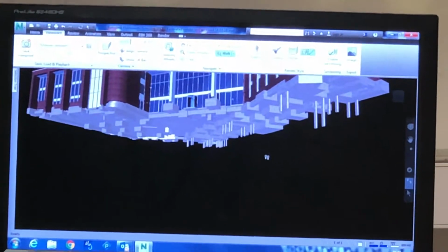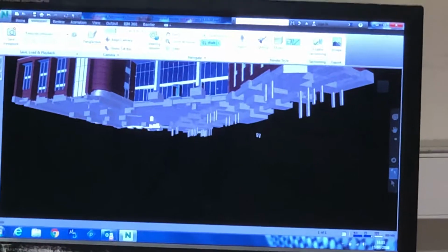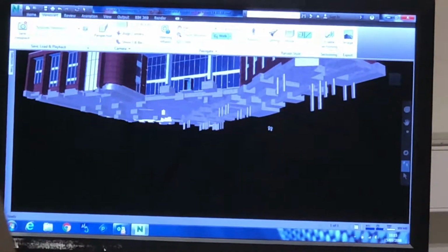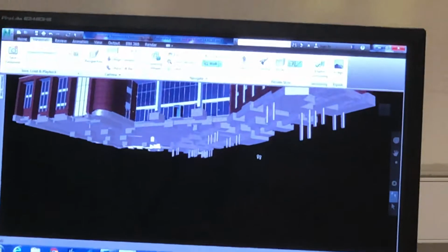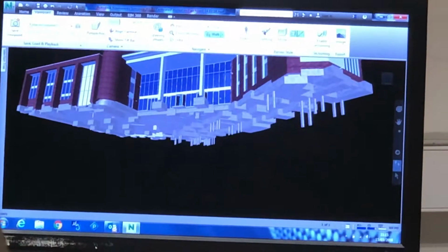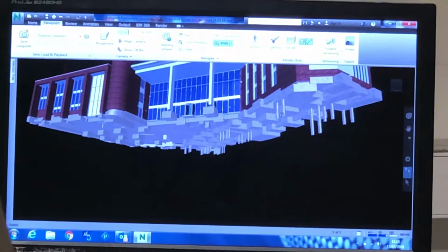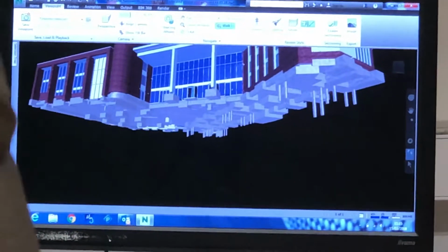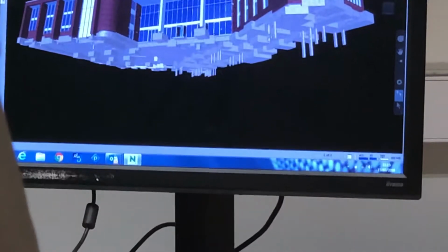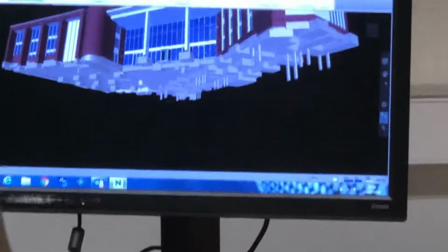There's 48 piles that have been installed to a depth of 6.5 metres, and they are 450mm in diameter. In each of the cores, there is a lift shaft or a double lift shaft and a set of staircases, and then the floor plates run in between them. So think of any sort of tower, they provide the stability, they stop it going from side to side, and the floors give you your lateral stability.